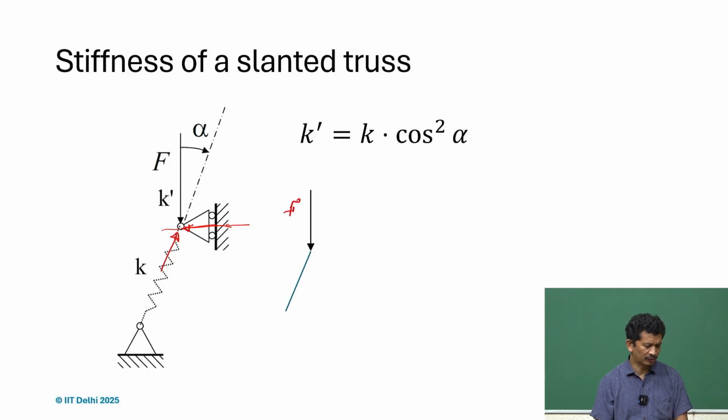Since this member, this link, call it a link or a spring, has two revolute joints, what we know is that it's a binary link, and for any member which is connected only at the ends with revolute joints, under equilibrium, if there are no other forces, the forces will always be along the longitudinal axis.